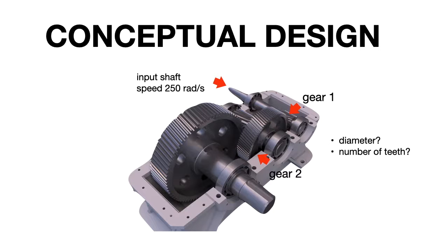Okay, so for example, if the smaller gear is connected to the driving shaft or the input shaft, then the output gear with the bigger diameter or more number of teeth will have lower speed and higher torque. Okay, so that is how you control the speed of a system by using multiple combinations of gears, which you will learn in the future chapters.